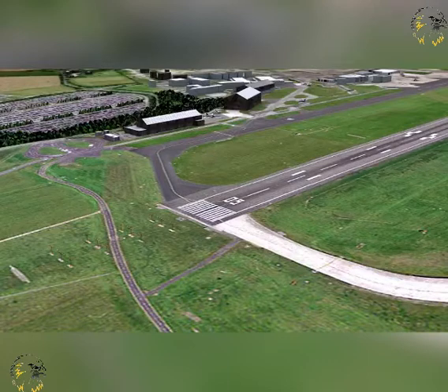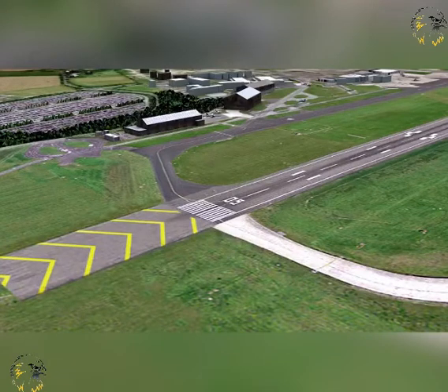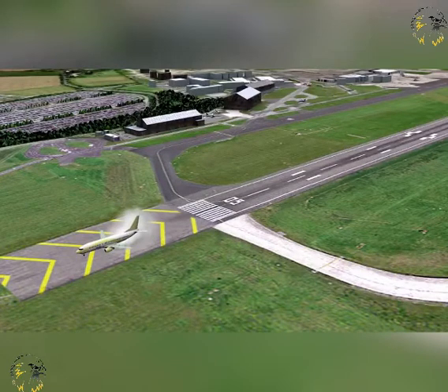For commercial and operational reasons, there may be an extension to the runway called a stopway. A stopway is a defined rectangular area beyond the end of the takeoff run available, which is defined later, in the direction of takeoff, no less wide than the runway and centered upon the extended centerline of the runway. Stopways cannot be used for any purpose other than bringing an aeroplane to a stop after an aborted takeoff. Therefore, they cannot form part of the landing or takeoff surface. To help the pilot recognize the stopway, it should be distinctly marked with yellow chevrons, as shown here.